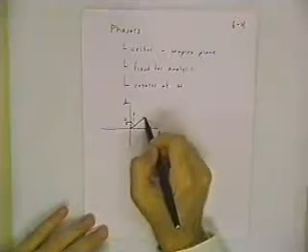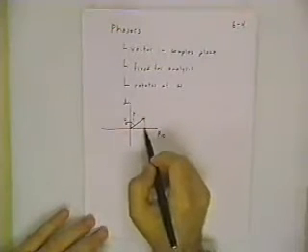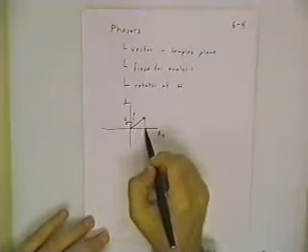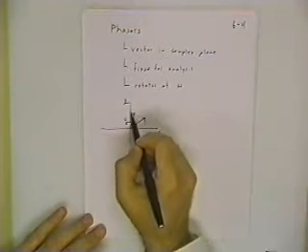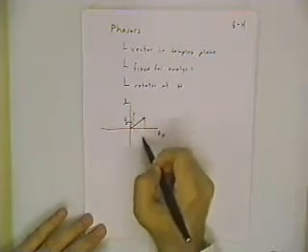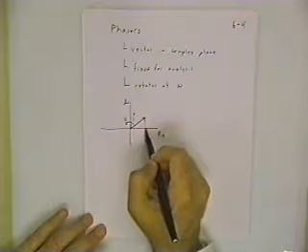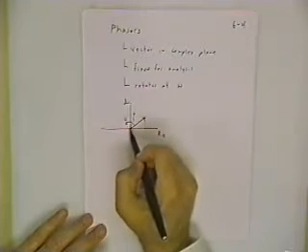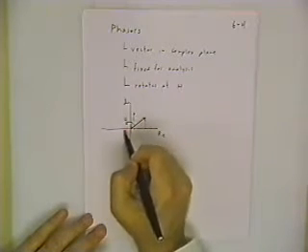And that's the idea, linking together this phasor, which is the complex vector, with the actual real physical thing, which is the projection onto the real axis. And as this phasor rotates round and around this unit circle, the projection onto the real axis alternates between negative, positive, negative, positive.